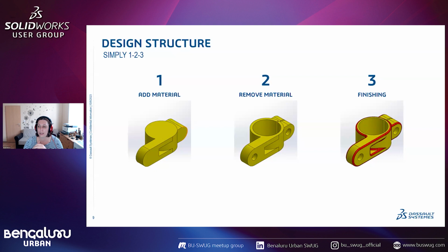Then you have these design fillets, which are more for finishing purposes. And these ones you put definitely always at the end. The reason for that is, first, for rebuild, it's faster. A fillet requires more calculation, and actually a feature after a fillet requires more calculation. And this is confusing a lot your mates. When you're making relations to a fillet, you remove the fillet and everything is breaking afterwards. So you have to avoid that.